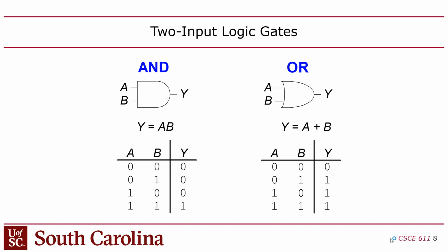And what ends up happening is that that module will be pulling up or pulling down. There's a transistor in there that's going to pull it up to VDD or pull it down to ground. And so if you have 2 modules that are both trying to output to the same wire, and one of them pulls up to VDD and the other one pulls down to ground, you end up with basically a low impedance path from power to ground, which will sink a lot of current and heat up the chip, possibly damage it. But it also will put that net, logically, into the forbidden zone, which is halfway between VDD and ground. It'll be an undefined value. So you don't want to do that.